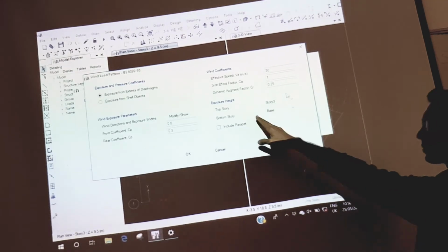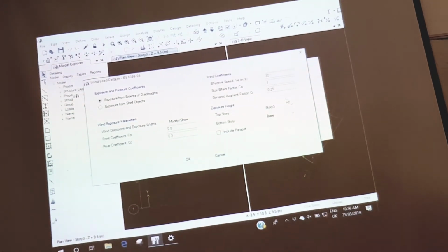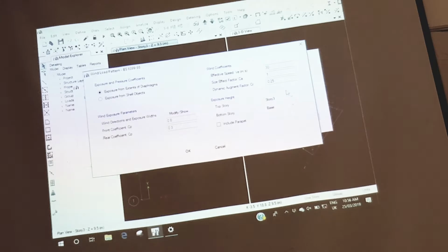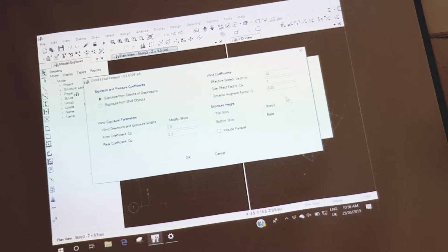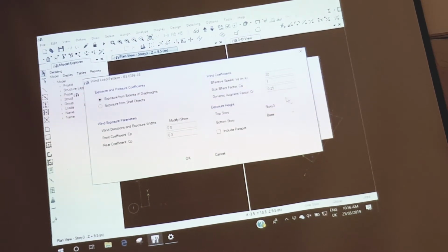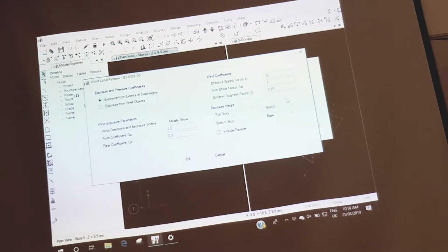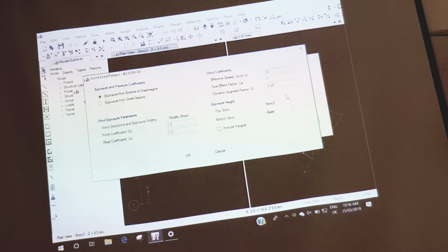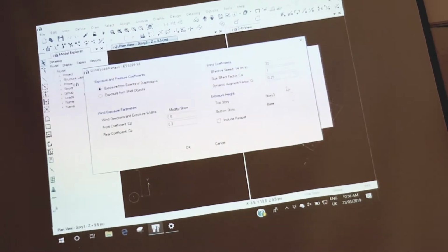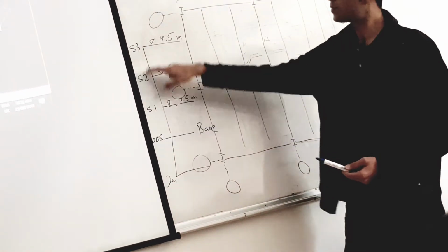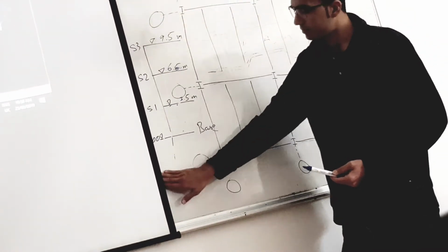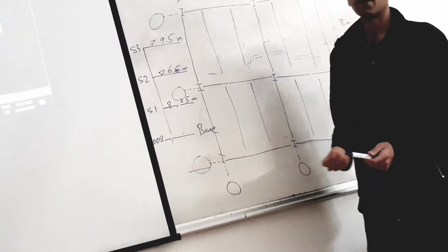And the most important part here is that if you see the elevation of the building, the wind load starts from the base over here. What happens if I add one basement over here? Let us say this is minus 3 meters. Below ground level, is there any wind load? No. So you are going to select from the base, from 0, up to 9.5. Everyone got this point?